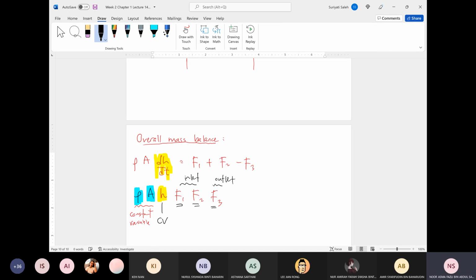Since we want to maintain the level, it will be good if we observe how the flow is coming into the system. So let the inlet come in and see how the level looks. Does it reach our value or not? Then we decide, based on the outlet valve or outlet flow rate.